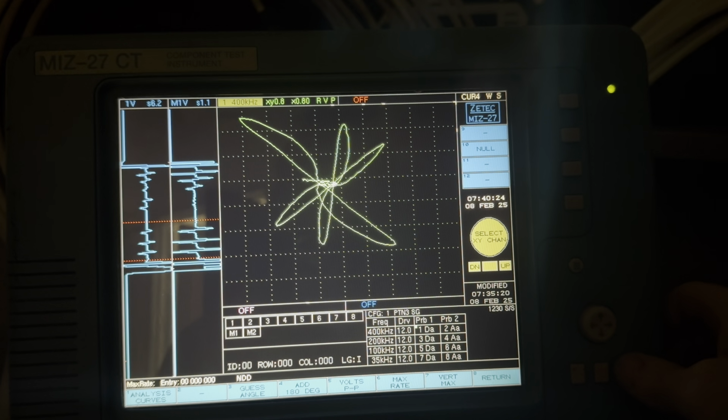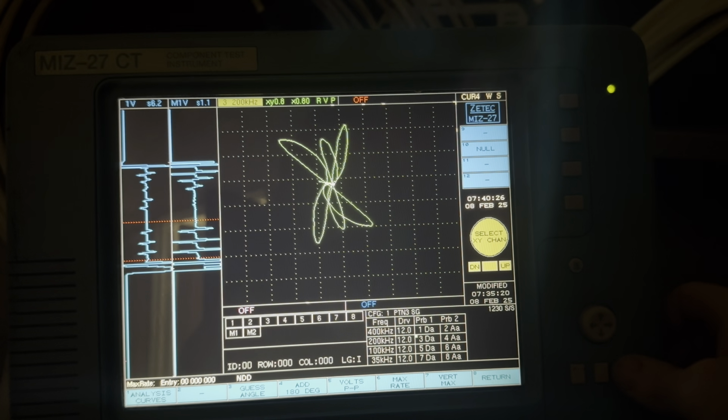Okay, so we use F90, which is this channel, for detection because most of the flaws will stick straight up if they're shallow ODs. If you want to size those flaws, ASME code requires that you use a channel that gives you more phase spread. Many of the code years say when you set your 100% hole to 40 degrees, the signal from your 20% flaws has to be between 50 and 120 degrees more phase, like from the 40 degrees from your 100%er.